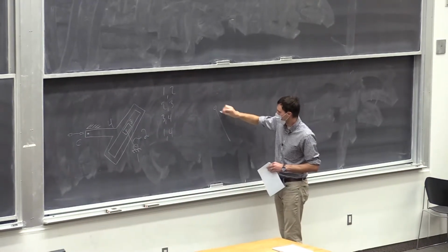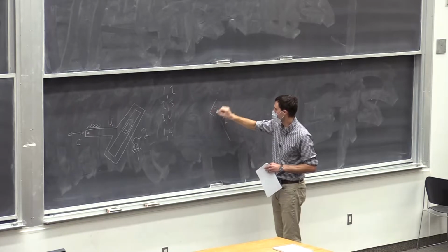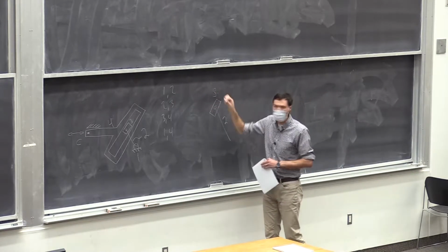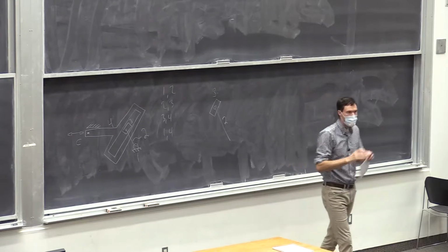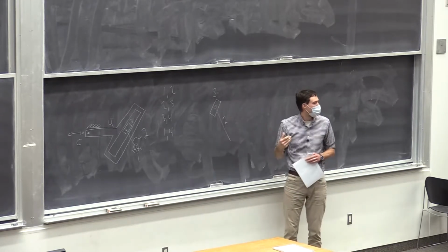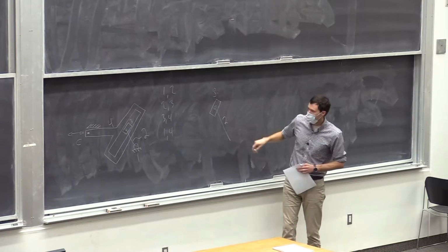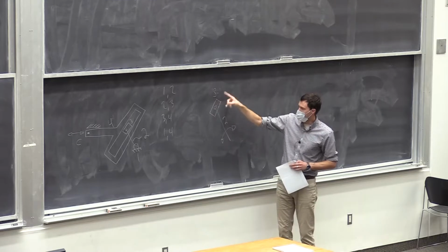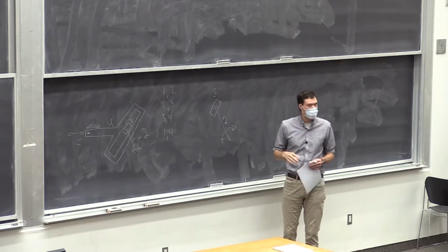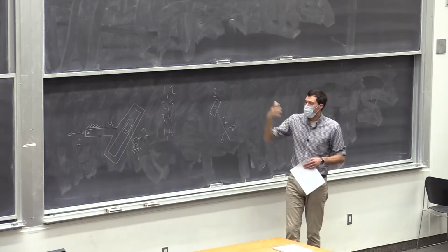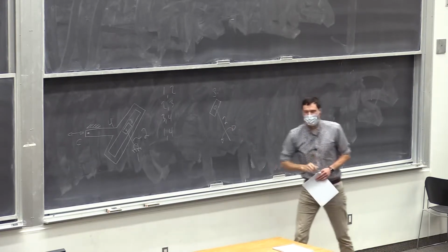So why don't you draw link 2 and link 3 off by themselves like this? That's a great way of isolating what's happening. When I draw it like this, we can see that it's just a turning pair connecting link 2, which is going round and round one way or the other, to link 3, which is just a block. Okay, so go through all these combos, make sure you understand how they're working. Then the next step, and I'll take your question in a second, sorry.